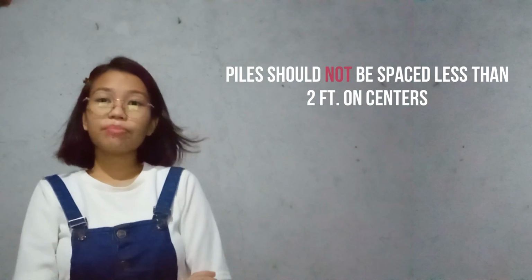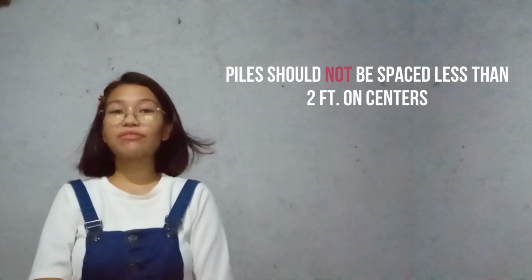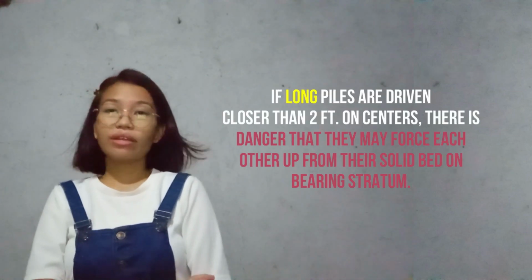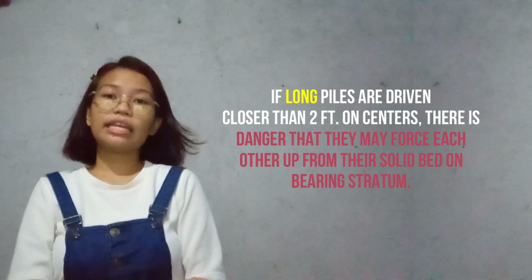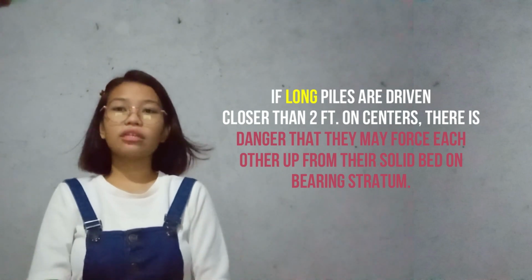The piles should not be spaced less than 2 feet on center. Usually, spacing is from 2 to 3 feet. When long piles are driven closer than 2 feet on center, there is danger that they may force each other up from their solid bed on the bearing stratum.